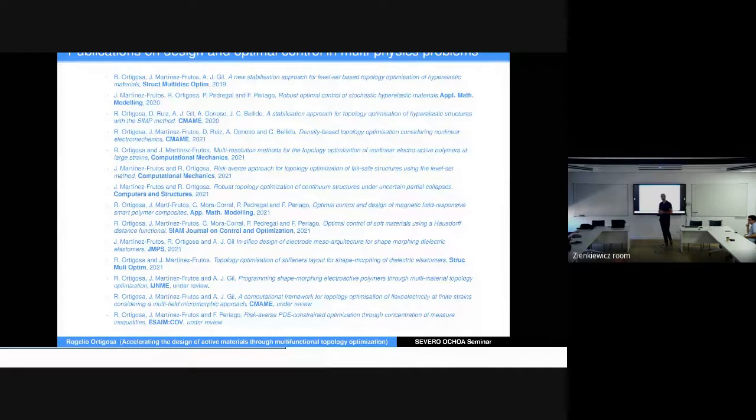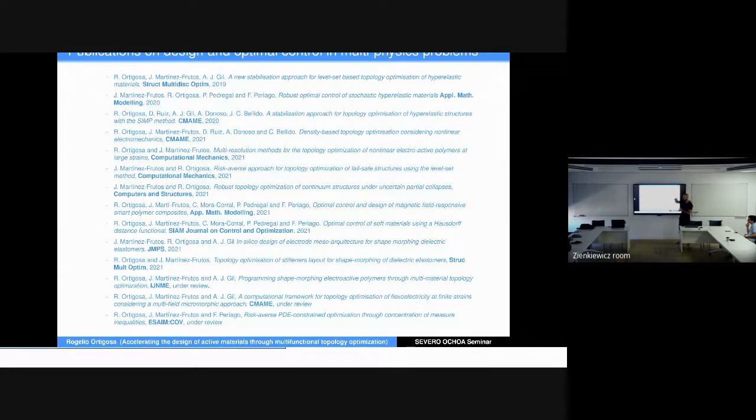So the problem of designing structures that are multistable, like mechanical switches, would be very challenging. It would be. Well, you can use tricks as well. In those cases we were in mechanics, using force control, so we were applying force. But if you go for displacement control, things are a bit easier. Still, you are going to have challenges, but in displacement control things are a bit easier. In force control, if you want to rely on an arc length method, you're going to go through a serious nightmare. That was my initial state with topology optimization, and it was not pleasant.